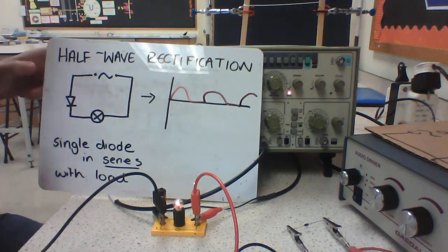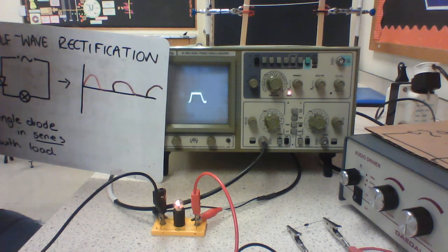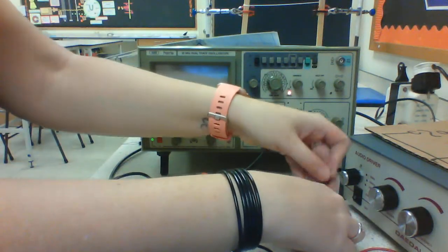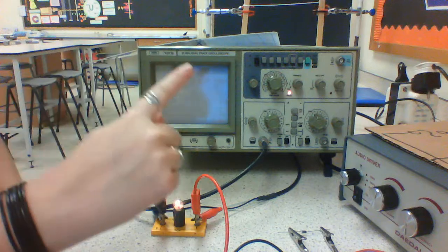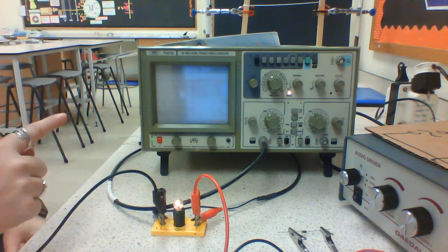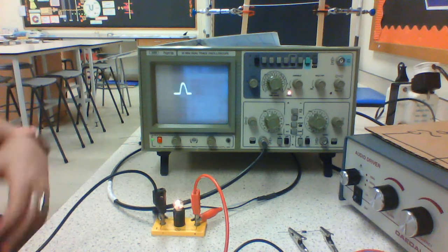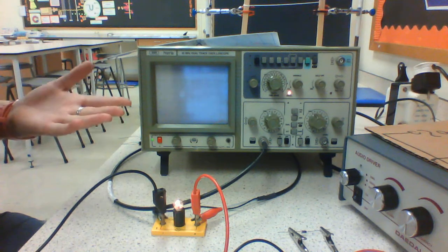Yes, it can be negative. That would be because I've connected the diode in the reverse bias. So if I've said the electrons are moving that direction, if I connect the diode backwards now, I'll get the opposite half-wave rectification, positive half-wave rectification. Now the electrons are doing move, break, move, break. That's half-wave rectification. Not brilliant because every half cycle I'm not getting any current.